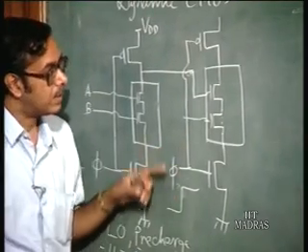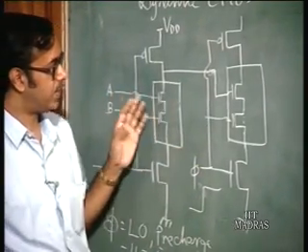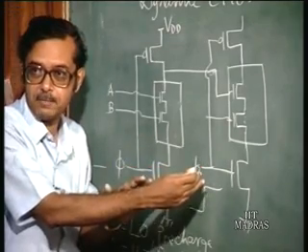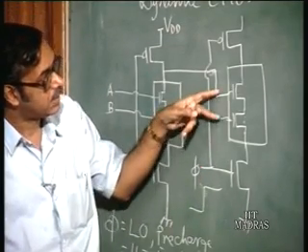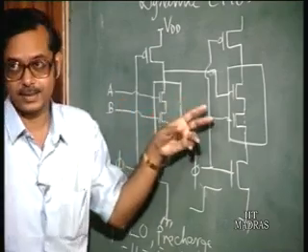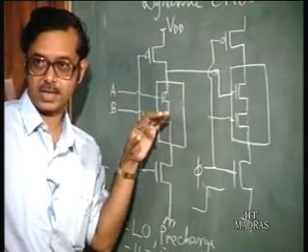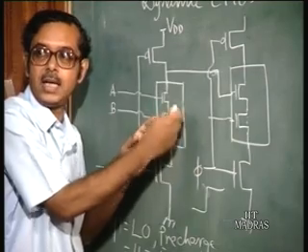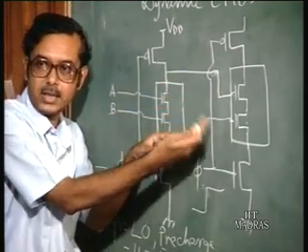So all the clocks go high simultaneously. Before this input has time to react to the changes in the previous gate, first this output must change and then effectively the other output must change.